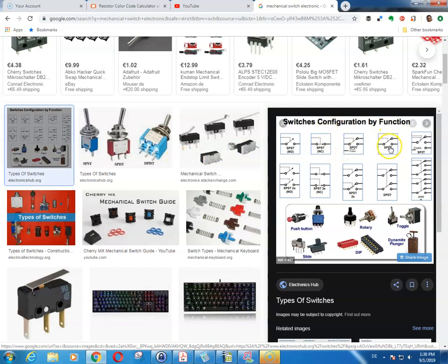Now there is another thing over here called a single pole, for example, double throw switch. So a single pole double throw switch is this kind of switch. As you can see, you have only 3 poles, 3 contacts over here, and one of the contacts is common between the two, meaning that in one position the common is connected to the contact up here.